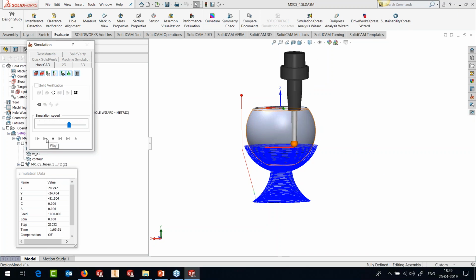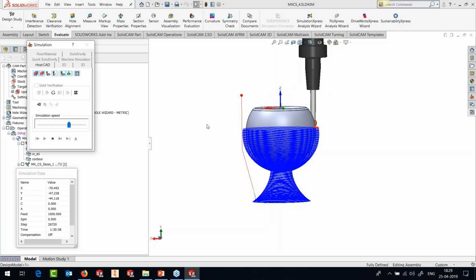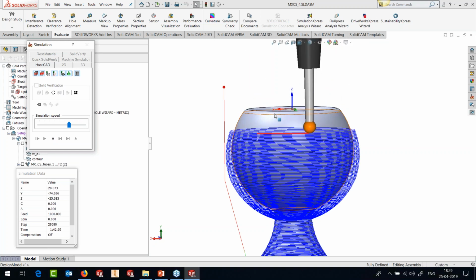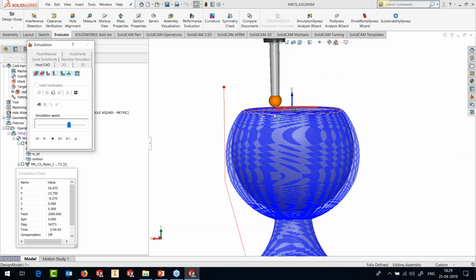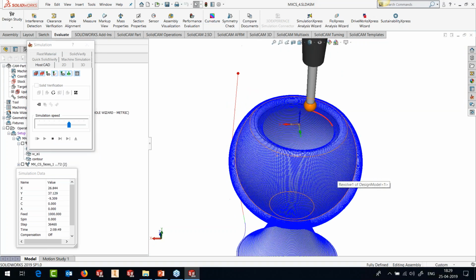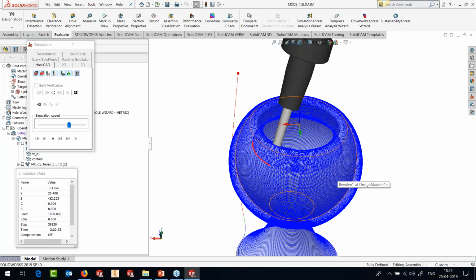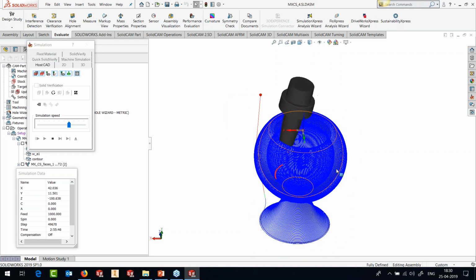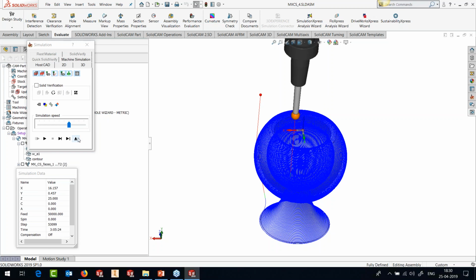And here again, we have used what we call auto tilting. Here it's almost 3-axis as it comes up. It starts going inside, and again starts generating 5-axis toolpath. Very nice, neat toolpath, extremely clean toolpath. The best part is that being a single toolpath means you will not have any mismatches of surfaces. Consistently, you can get a very good surface quality.